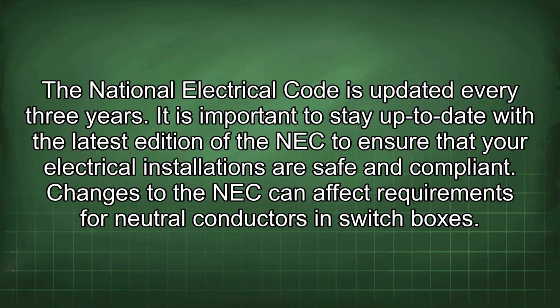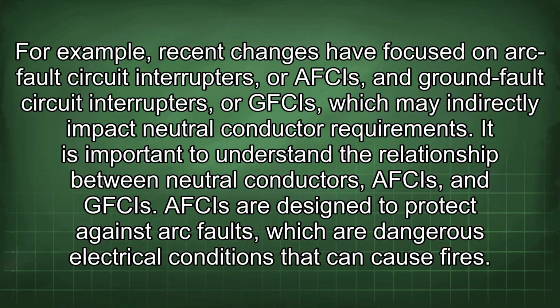The National Electrical Code is updated every 3 years. It is important to stay up to date with the latest edition of the NEC to ensure that your electrical installations are safe and compliant. Changes to the NEC can affect requirements for neutral conductors and switch boxes. For example, recent changes have focused on arc fault circuit interrupters, AFCIs, and ground fault circuit interrupters, or GFCIs, which may indirectly impact neutral conductor requirements.